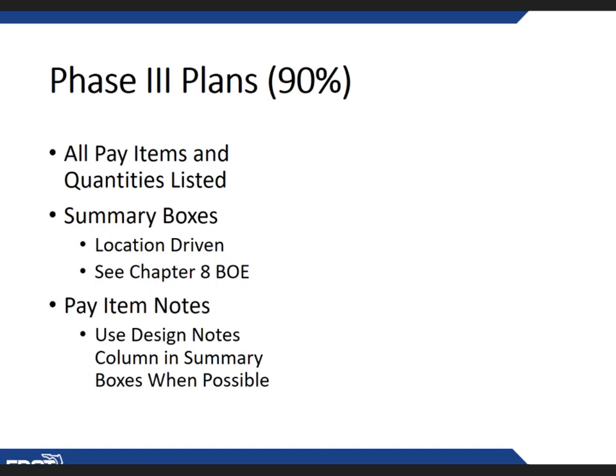So for location-specific pay item notes, consider using the design notes column in the summary boxes. For example, the size and the shape of a concrete pad that differs from the design standard. You could put that information in there. At 90% plans, all of your tech specs should be completed and finalized.